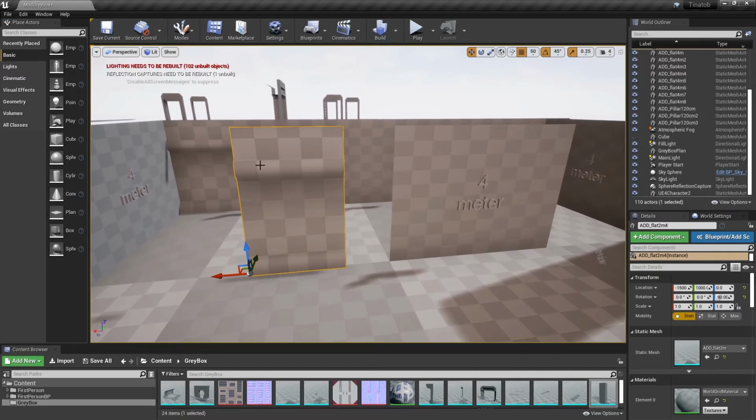So obviously, as I iterate and develop this piece, as I do another pass and another pass, keep your file of the FBX the same. You can save iteratively in your max files. In fact, I encourage you to save iteratively in your max files. But when you actually save out your FBX, just overwrite the file. Unreal will detect the update, and it will update and propagate around the level.